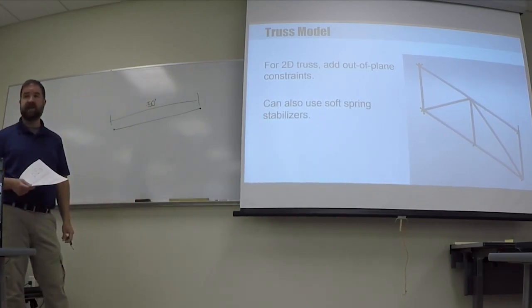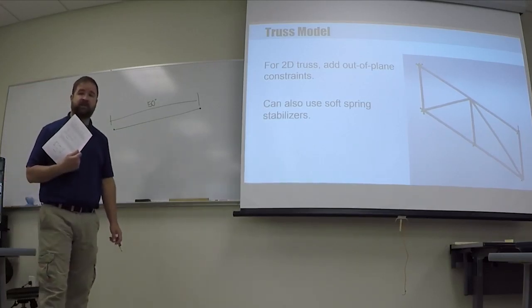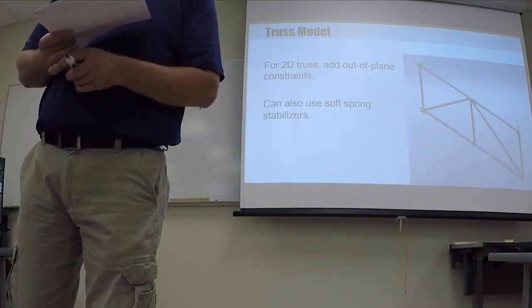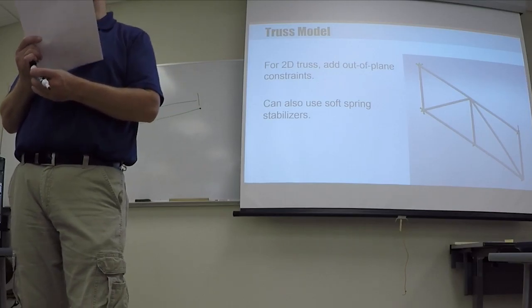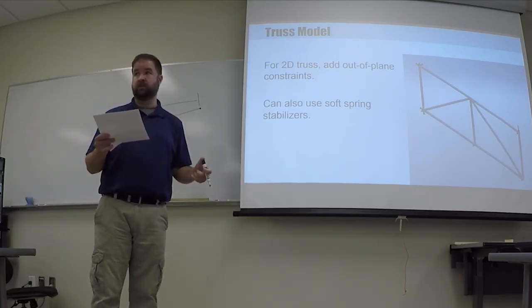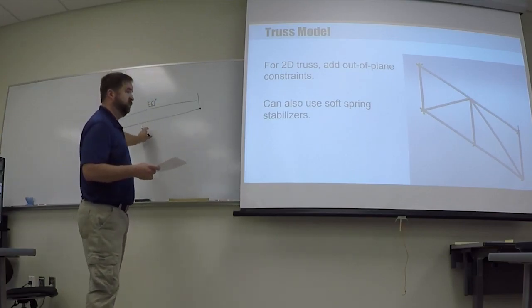And that's all you have to draw in SolidWorks. Just in a sketch. Now, to get it to do beam elements, you have to use the weldments capability in SolidWorks. Have you guys used that before? So, you draw a sketch of a line.